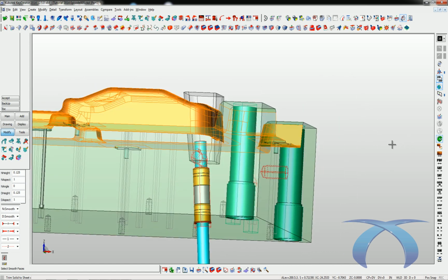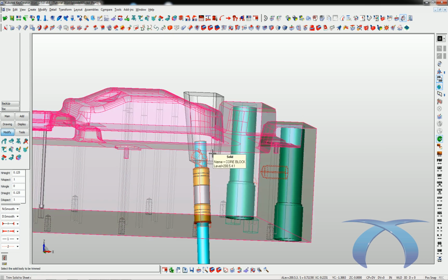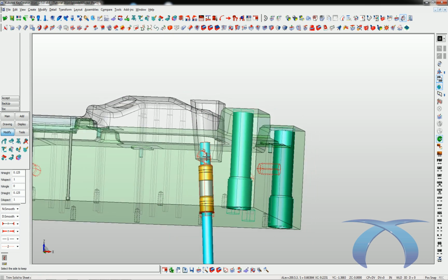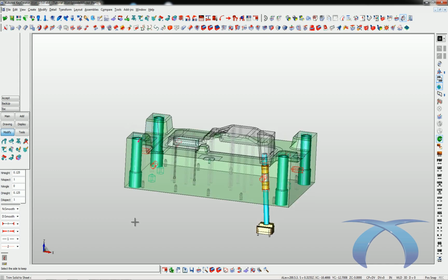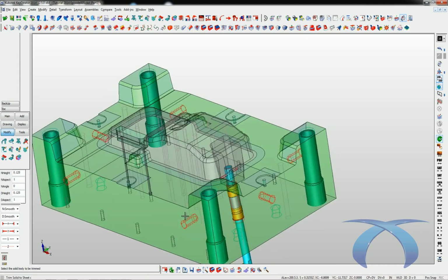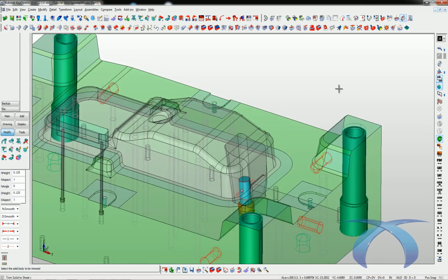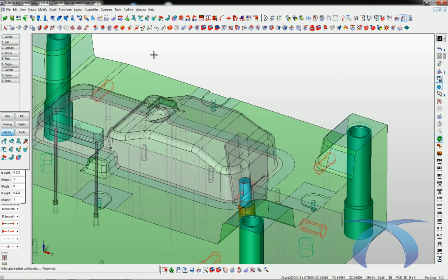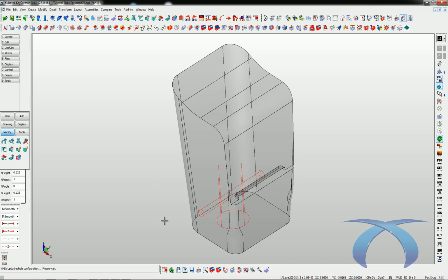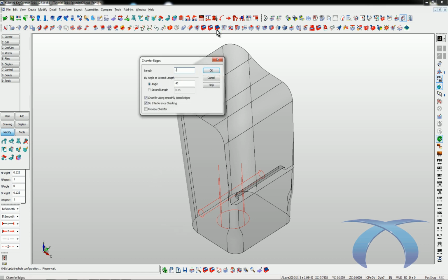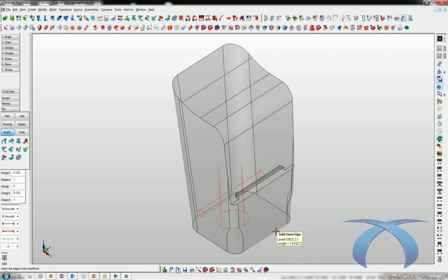So I'm going to go ahead and say accept to that, and then I'm going to select the solid that I want to trim, and I want to keep, obviously, the part towards the back of the lifter, and that's it. I have my lifter complete just like that. So very easy, very quick. Got my lifter like that. So now what I want to do is I'm going to put a little chamfer at the bottom of that lifter, so it's not left sharp.